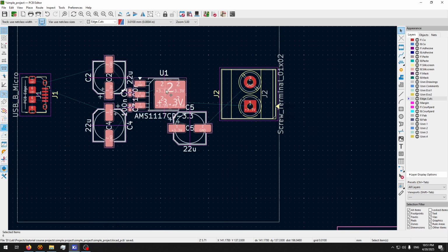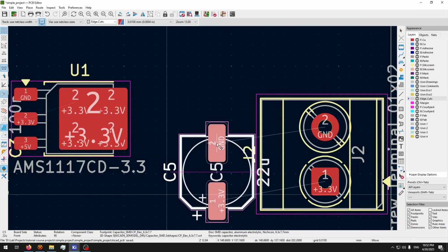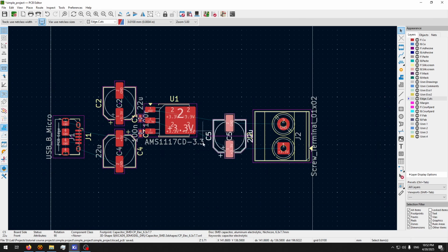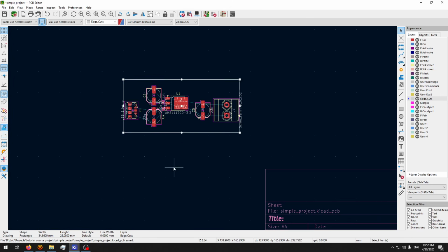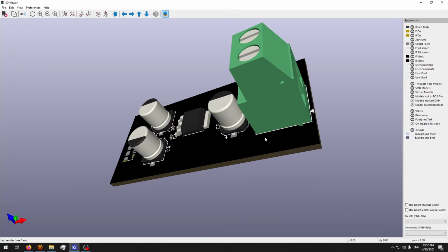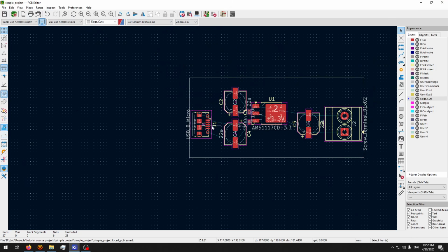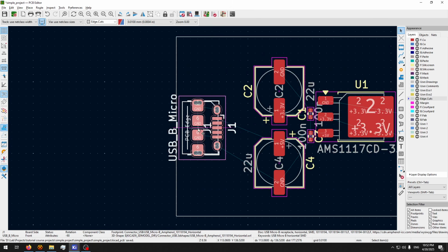Let's make room for the new capacitor, maybe like this. And the new capacitor is basically going to be connected right here to make a shorter path. So now let's make it even tighter, like this. Okay, so Alt and 3, you can see it is perfectly fine except for this. Okay, let's try to move it to maybe the center. You can basically fine-tune it forever.